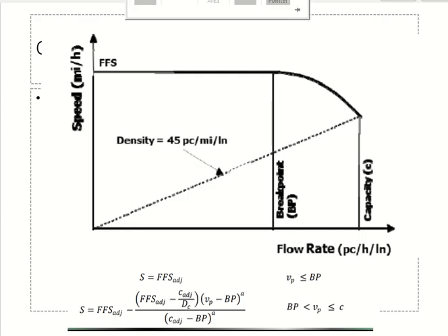When density is 31, we know that the level of service is D. We found it in the last example as well. Now for the upward, you will recalculate S. Only VP will change for the upward. The rest of the items will remain the same. And then you get new S and new D. You can finish it off, but it is almost the same.